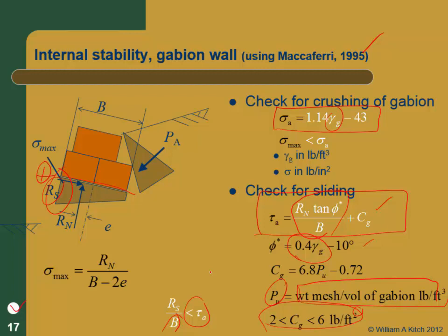If you're expecting to hand place all those things in there, and you're down to a porosity of 35, and you found the guys are just bringing an end loader and dumping it in the gabions. By the way, you don't want to just dump in the gabions anyway, because you're going to bend the wire on the sides. You've got to be a little bit careful about how you place it, because otherwise you're going to deform the gabions, and then they don't stack straight, and they don't go upright, and then you got a big problem. So you can't just dump into a gabion anyway. There has to be some handwork there. So that's a great question. Never built one, but definitely something you want to be concerned about.